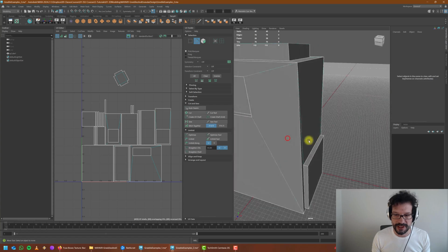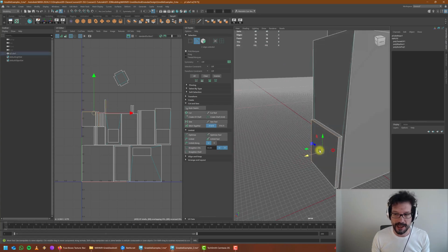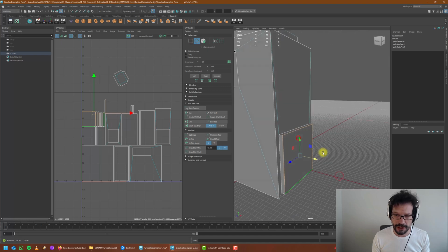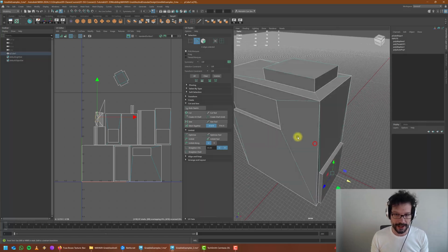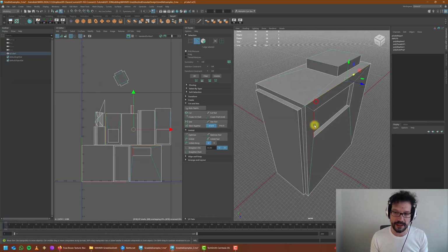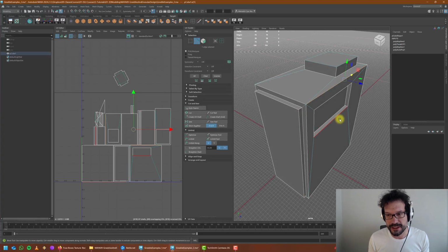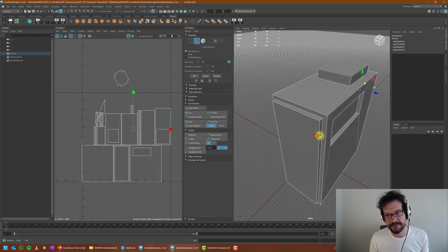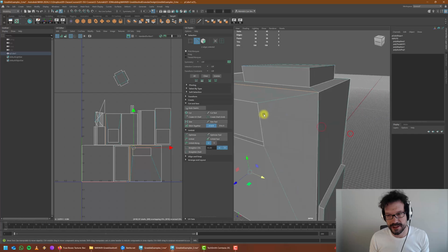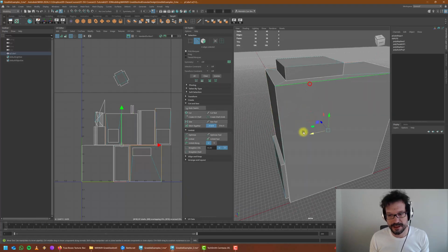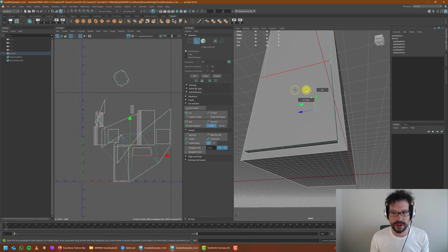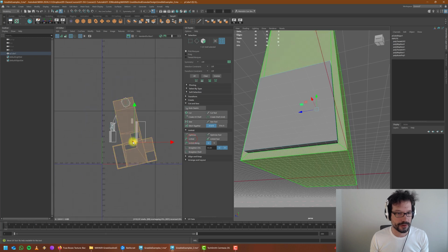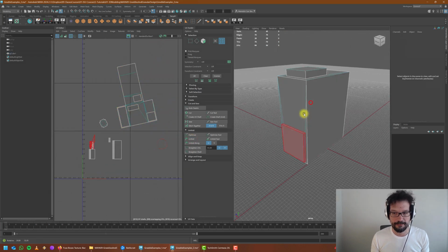That is another approach. Instead of starting with an uncut piece and cutting it yourself, you can start with an almost fully cut piece and start stitching things together, and then unfolding them to get the correct orientation. So let's do the same for here. Let's stitch most of these pieces. For example, we can stitch these, we can stitch that, and we can stitch that, and we can leave the other one empty. So when we go to UV shell and unfold, ta-da, it has unfolded very nicely.